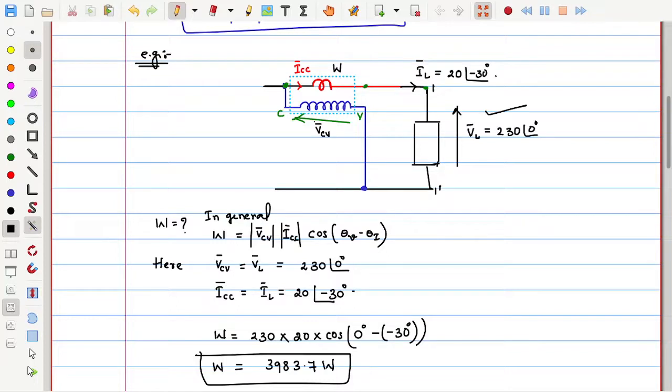Similarly, voltage coils are analogous to voltmeters. Voltmeters are connected across the element, in parallel, to measure the element voltage. So just try to see what the voltage coil voltage and current coil current are. Once we know these two, it is easy to find the wattmeter reading.